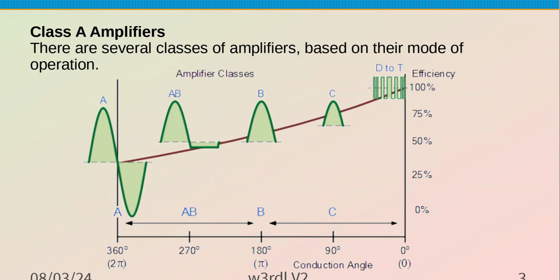It comes close to 100% reproduction of the input signal waveform, but it's the least efficient because you have to bias the transistors in the linear region, like about half of the voltage supply. So they're always conducting current, even when there's no signal. So less than 50% efficiency.